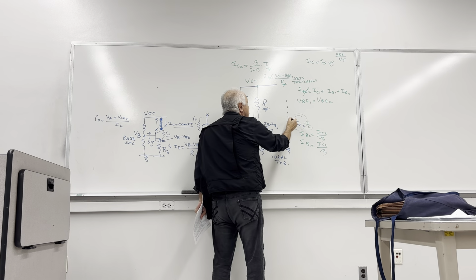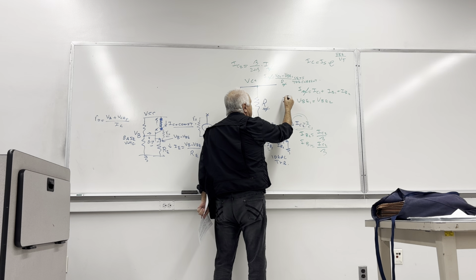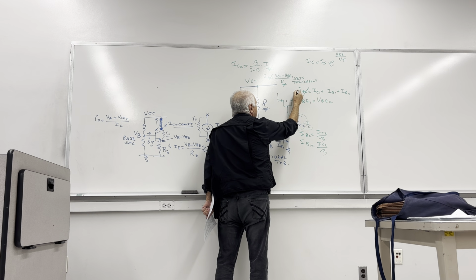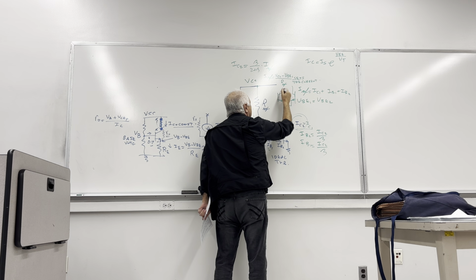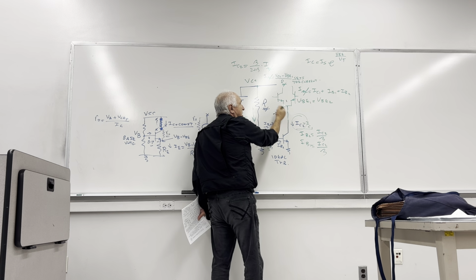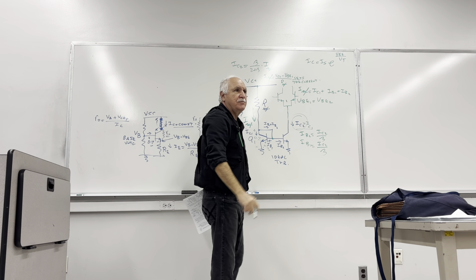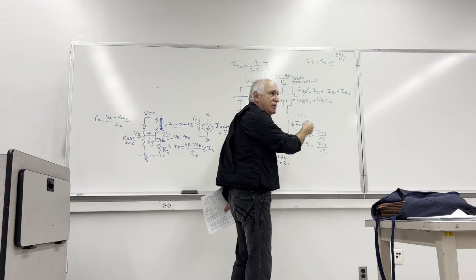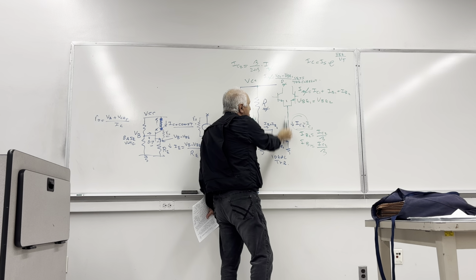It could be going to transistors, like it will go there, the differential pair, etc., or anything else. You see? This will be feeding the emitter current of both transistors. That's where I'm leading to. In a minute we will get there. So it is sending a constant current supplying to both.